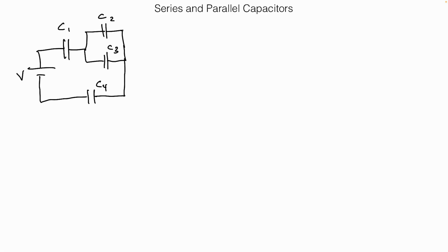Whoa. Circuit analysis is the art of looking at these pictures and being able to determine series and parallel connections. The way that we're going to survive it is by doing something called circuit reduction. We are going to attempt to reduce this circuit's complexity down to the simplest possible circuit.